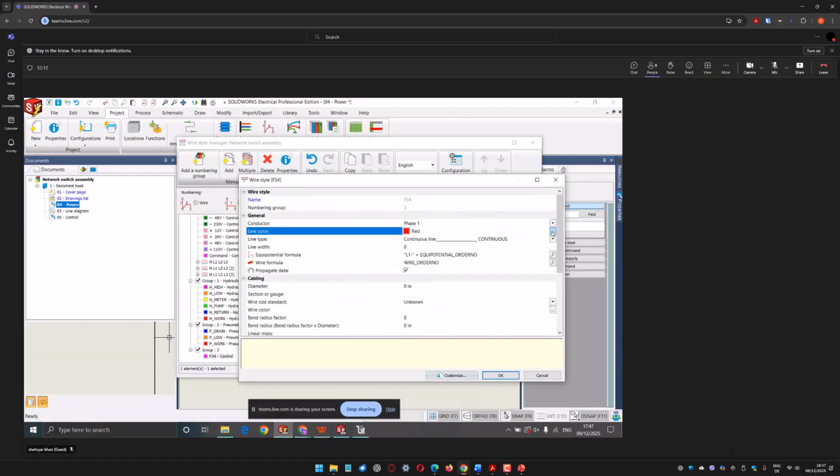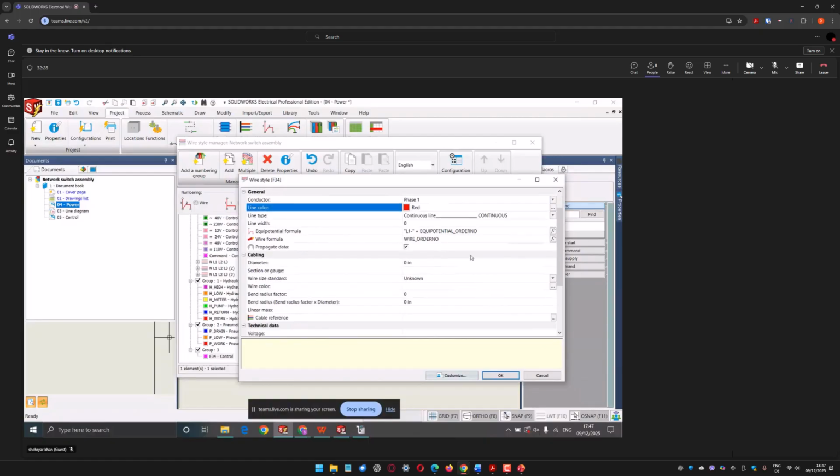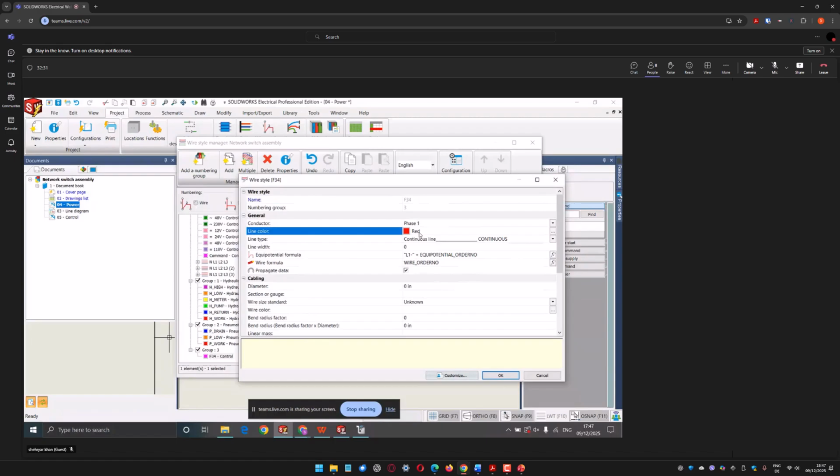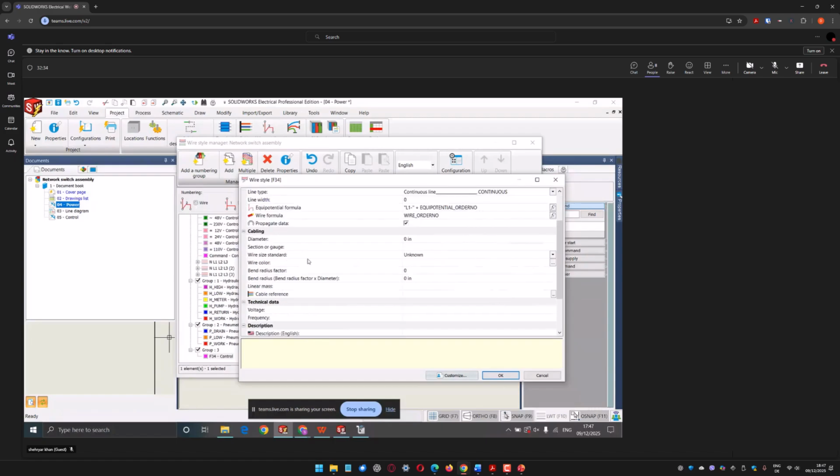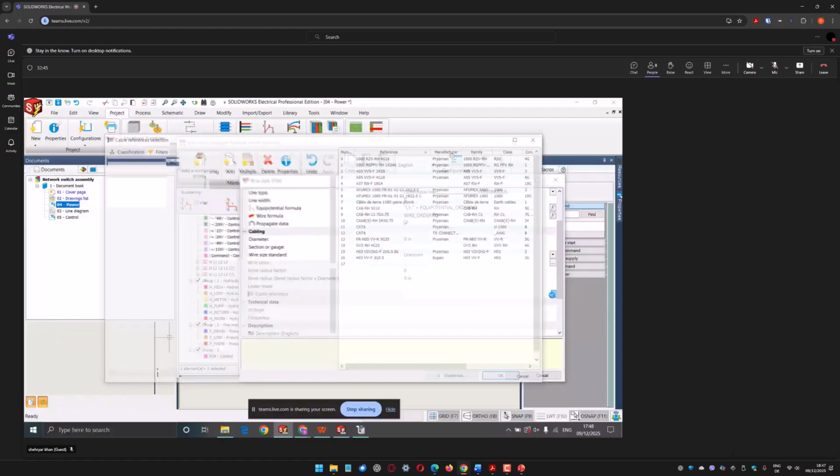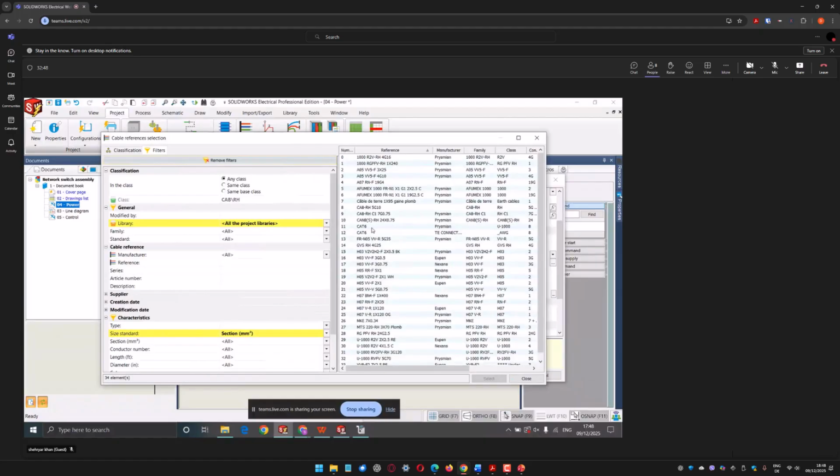And here, for example, I have the wire colors and the wire dimensions already defined. I'm not going to detail it because it will take a lot of time. We can just create 8 wires here and then insert them into our connector. So each color can be chosen for our line, and then the wire standard, the wire gauge and everything can be chosen, and also the cable reference can be done here. What type of cable we have for those 8, it's a Cat6. So I have created Cat6 already here, and we can choose from here.